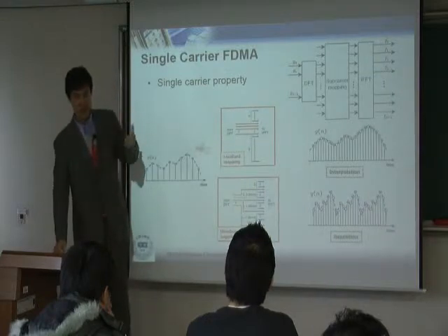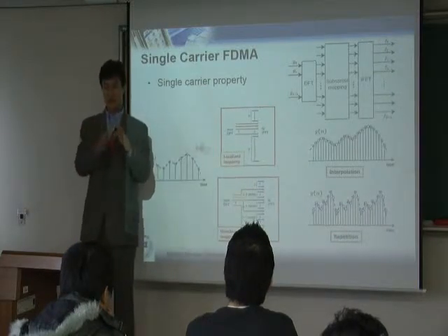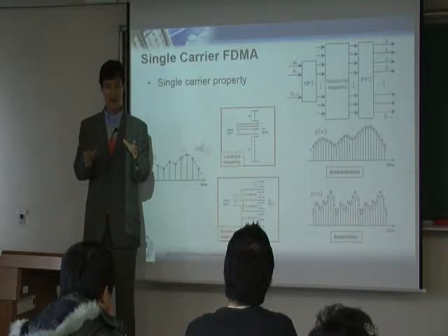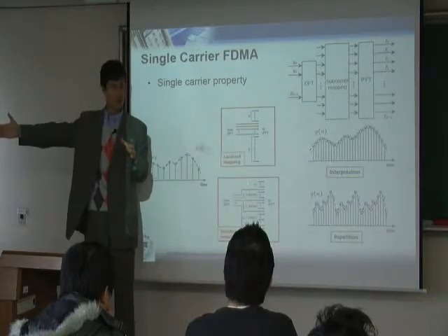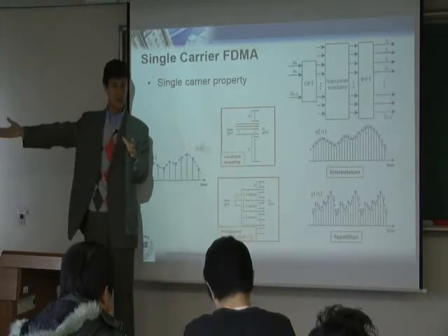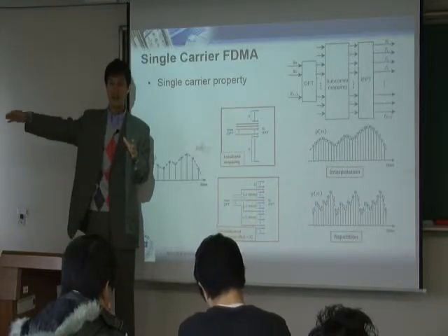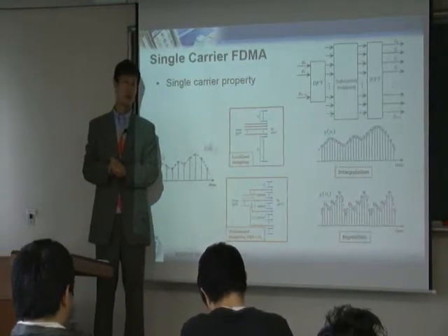Generally in signal processing, you have some number of samples in the frequency domain. You put zeros in the frequency domain, you increase the number of samples, simply doing zero padding, and then go to the time domain. Then what happened?